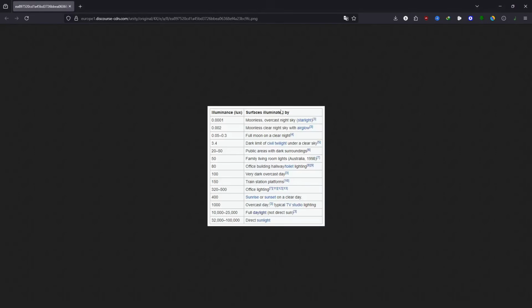Okay, and if I check here, you are going to work with the lux lighting system. If I open these lighting values here, you can see them as well. This is given in lux. So if I want to go for direct sunlight, it should be around 1 lakh, 1 lakh lux. Okay, so we are going to work with this, and I'm going to show you how you can use these real world lighting values here.